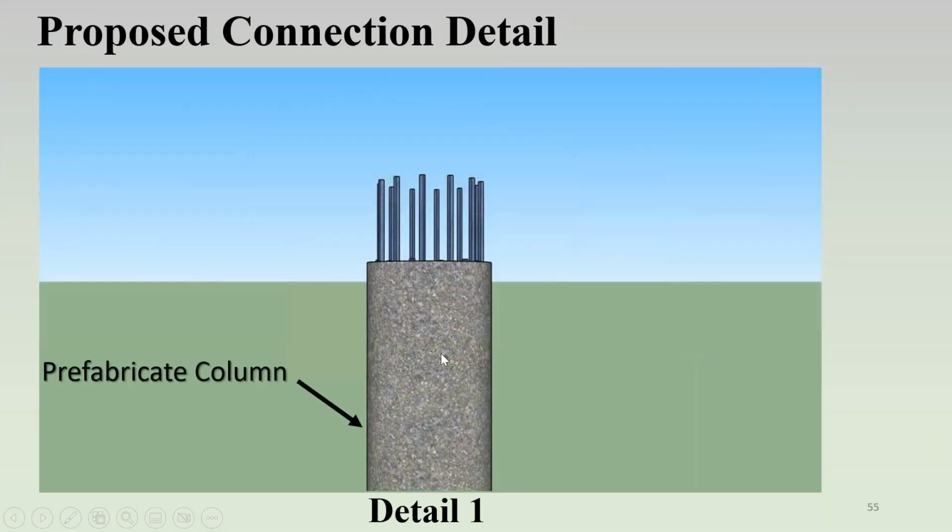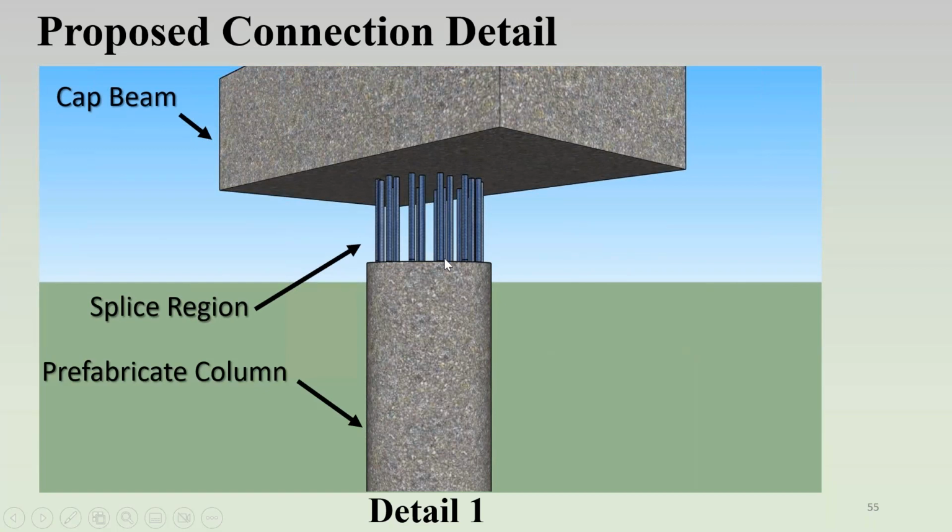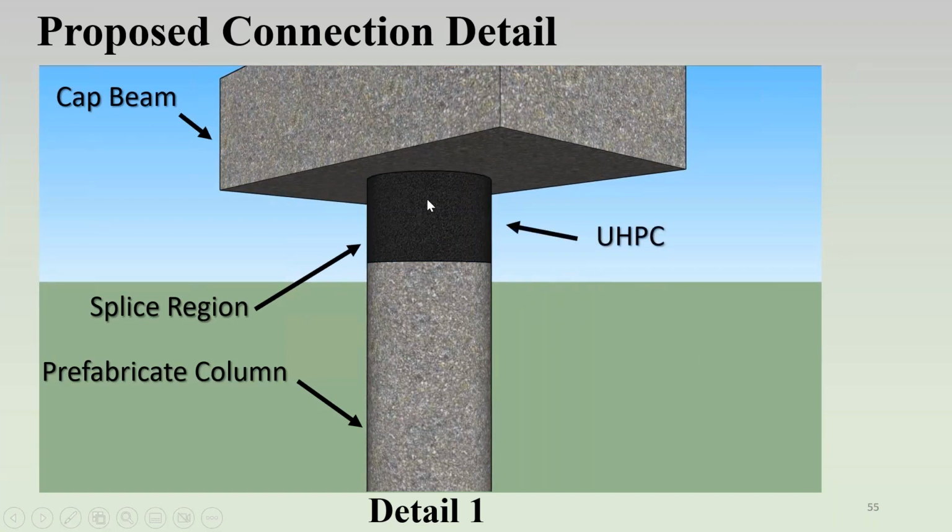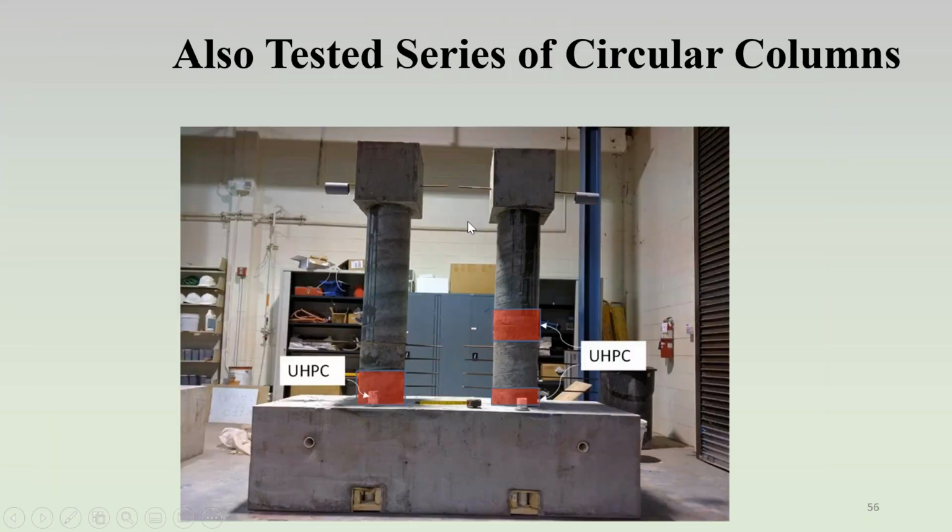Connections. Here is a connection where you bring two precast elements together, and then you cast it. Basically, you connect it with the UHPC. Dr. Stanton, in the previous presentation, gave one solution for the formation of the plastic hinge. In my opinion, UHPC needs to be used for moving the plastic hinge away. If I connect these two elements, the plastic hinge is going to form over here because nothing is going to happen there. There's another idea that I will show you.